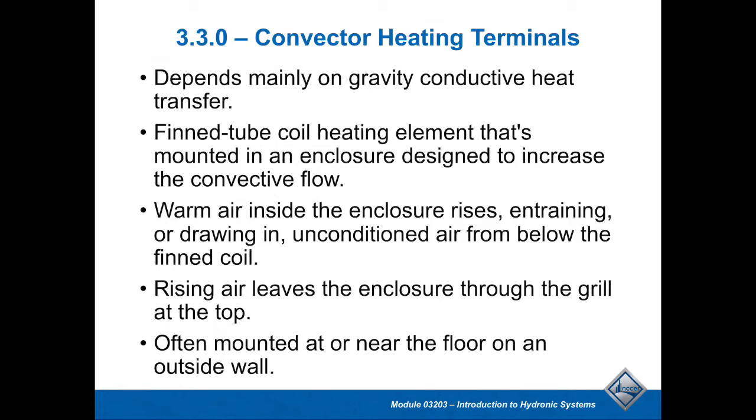A lot of times these will depend on gravity convective heat transfer, meaning they're going to take the colder air that's on the floor area and move it through and over the heat exchanger to allow you to transfer heat out of them. Now, that's one way to do it. They don't typically have a fan. That's usually what happens with convectors.